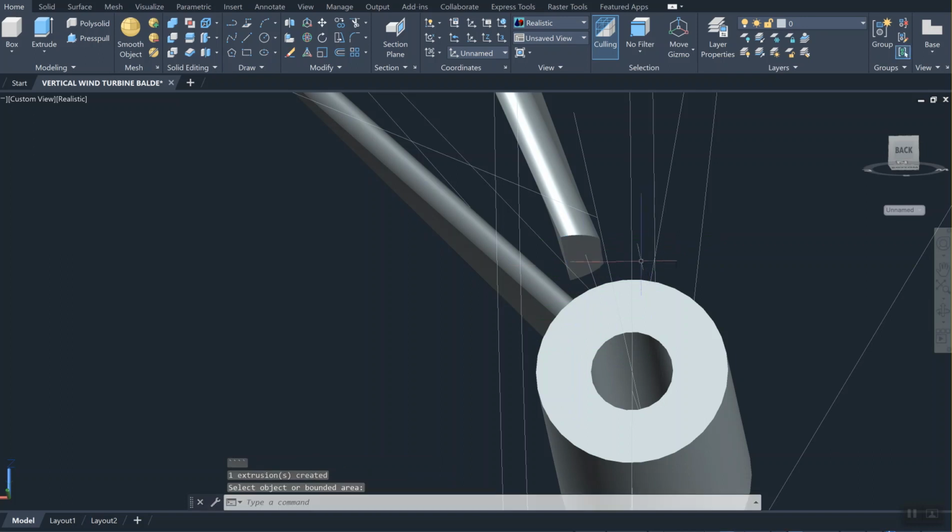All right. So before I do that, do I need to change UCS? Yeah, why not? And choose the surface of it. UCS again. Select the face of the object. Okay. You can say flip, Y flip, X flip. Enter. It is still not in the same direction I like to have.